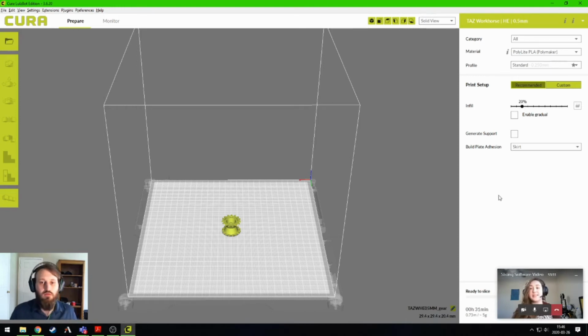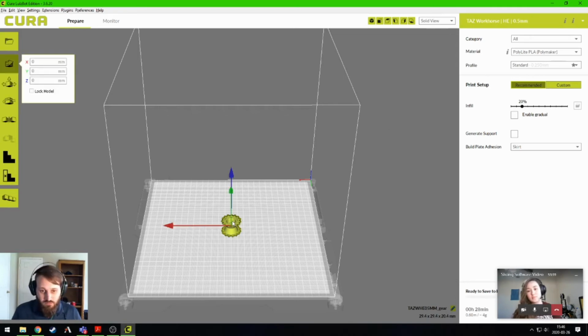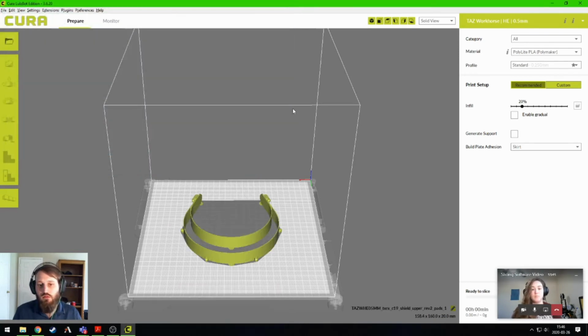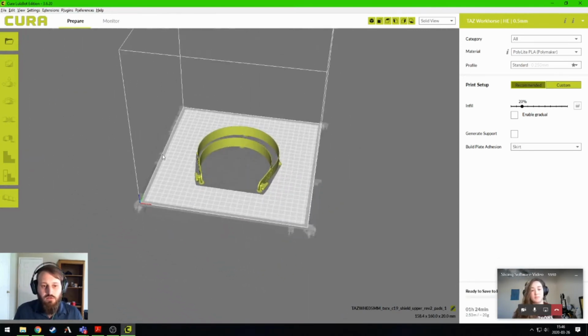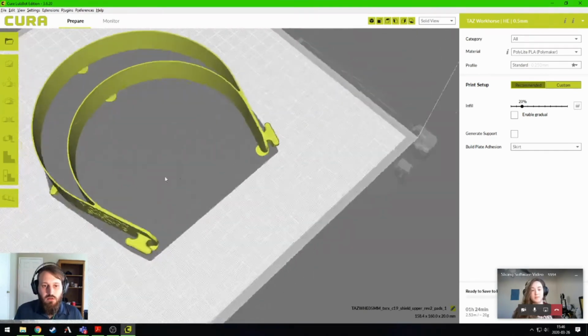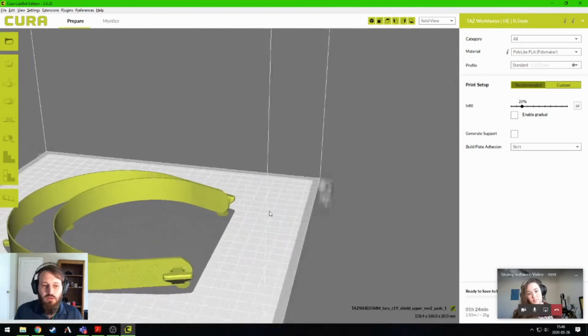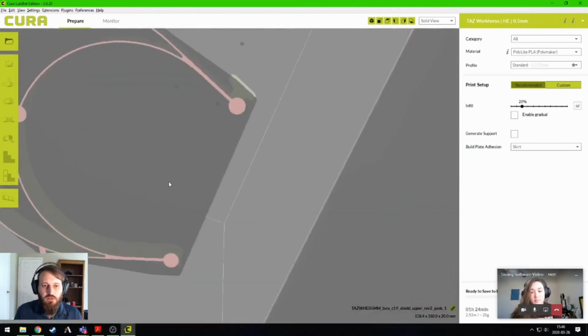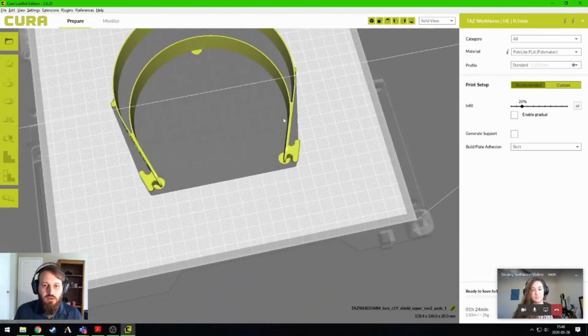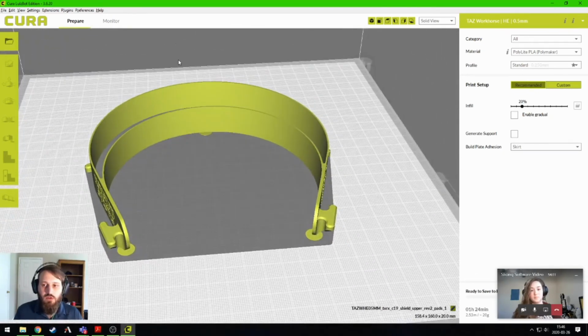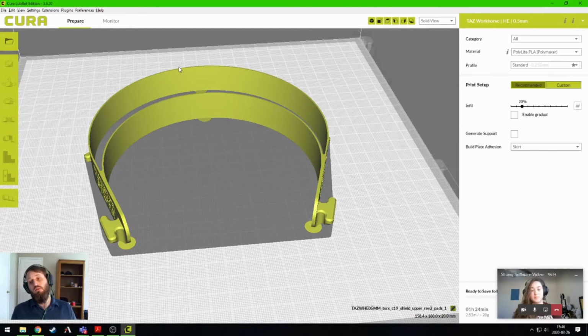What objects would you recommend doing anything less than 100% on? I actually have one. This one came through from the TXRX Labs build. This is one of those face mask headbands. You don't really need infill for this. It's too thin. You can just do bigger walls. So with something like this, we wouldn't need an infill setting. That's just because it's simple bands. Something like that, it's too narrow for too much infill. So just thick walls would get you done there, where you have like 0 infill.